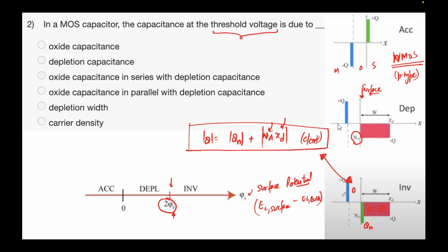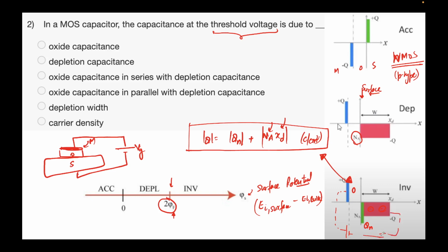But one of our terminals is here. So if you actually look at it, this is your metal, this is your oxide, and this will be your semiconductor. Metal oxide semiconductor. So what I am doing is applying some positive bias to the metal, VG, as we call it, and the source is, let's say, grounded or at the negative terminal. Just think of it, the circuit has to be complete. So it's connected to the positive terminal, and this is connected to the negative terminal. This is the complete picture actually.